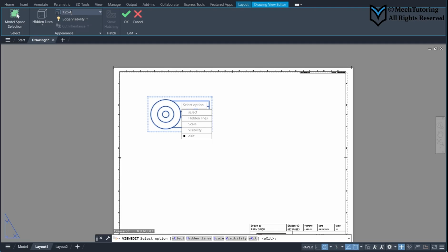We want to dimension it in millimeters, okay? So the scale we want to keep on the drawing is for the millimeters, because our template is in inches, okay? But the part we created was 25.4 times bigger because we created everything in inches, because the dimensions of the part given to us in the technical drawings were in millimeters. So that's why the scale has to be 1 ratio 25.4, okay?